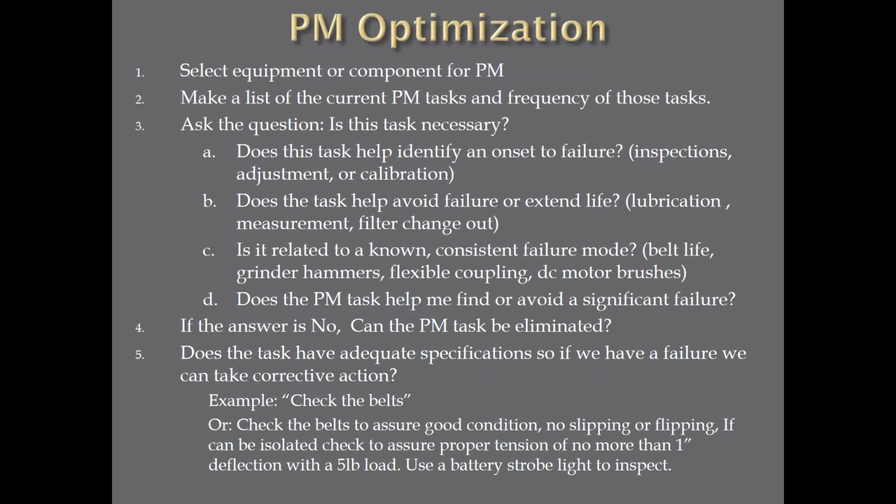So if you're checking V-belts, does it just say check the belts? My maintenance crew brought this up to me years ago. Well, what do you want us to check? It says check the belts. So I went over this thing about checking the belts for good condition, no slipping, flipping. If you can isolate it, do we use the tension gauge? What is that specification? Well, my maintenance guy says, yeah, but we're checking them when they're running.